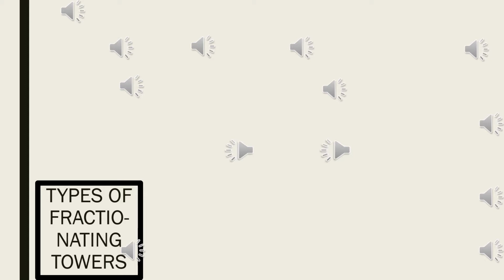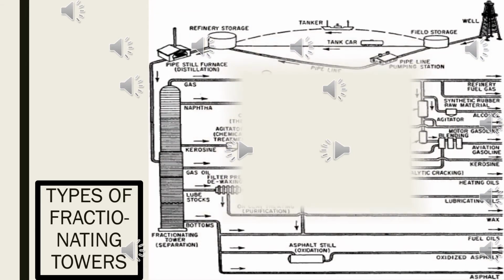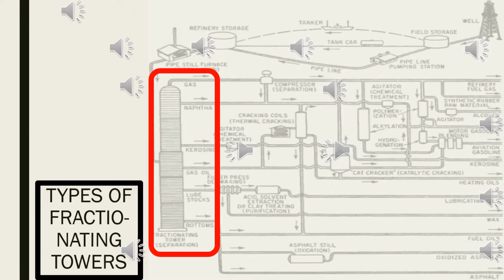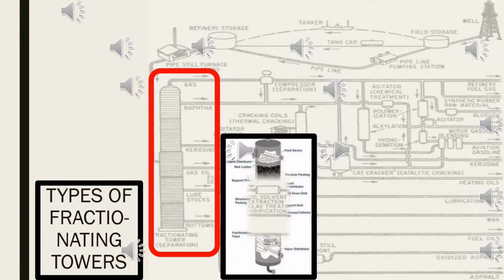In this slide, you will focus on the equipment that you can choose for the fractional distillation, the main process of separating the hydrocarbon components of crude oil. Firstly, you can choose a packed distillation column, which is filled or packed with material that allows rising vapors to contact descending condensate. The more the vapor-liquid contact, the better the separation. The material you pick for construction should be compatible with the crude oil being distilled.